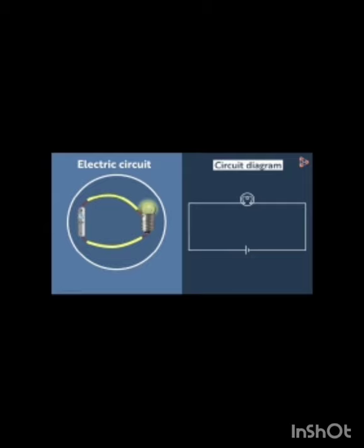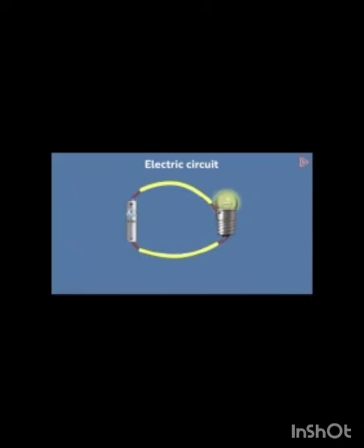It was simple to draw, wasn't it? You can even show the direction of electric current in the circuit with arrowheads. So the electric current is flowing in this direction, from the positive to the negative terminal of the cell. Now we had seen in the past that this is not the only way to light up a bulb in this circuit. For instance, if we interchange the wires connected to the two terminals of the bulb, then the bulb will still glow. This is because the circuit is still complete and all the terminals of the system are occupied.